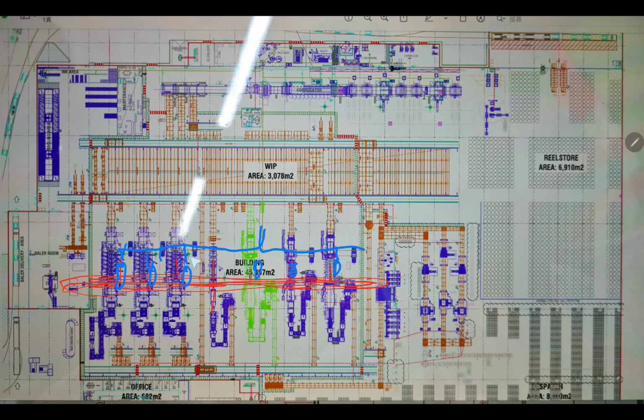The line is coming with gravity. We are not using any pump, because every time we need to consider our power and other things, to keep minimum manpower and minimum power supply. So we collect this single phase washing water 1 and washing water 2, double phase, and all this day tank is here. So all this water line is coming to collect in this manhole.